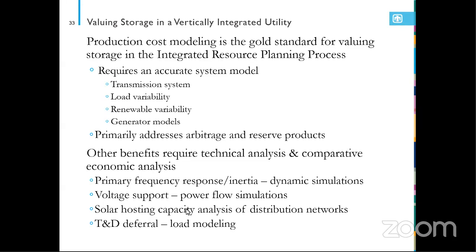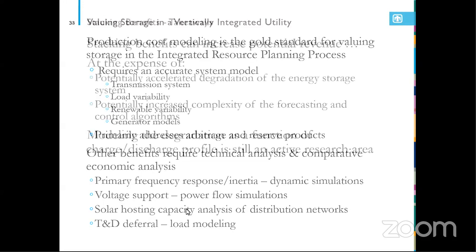In distribution networks, you have to do solar hosting capacity analysis to see when you're going to start to have problems with certain levels of renewable generation. And then for transmission and distribution deferral, you have to do load modeling and usually some power flow modeling. So it's really pretty complicated, if you're a vertically integrated utility, to make the case for valuing energy storage.